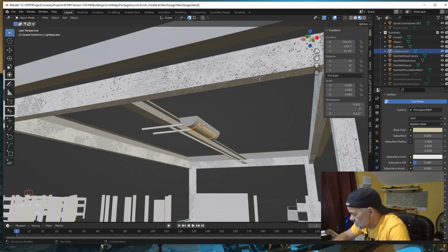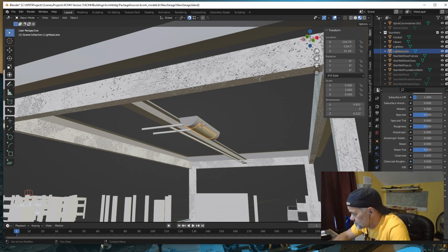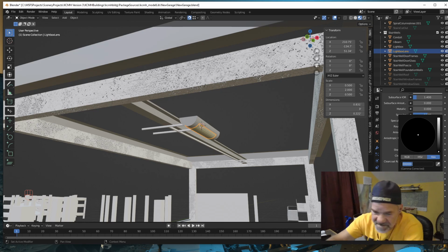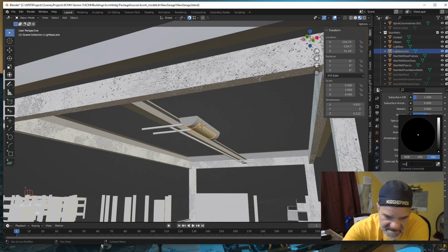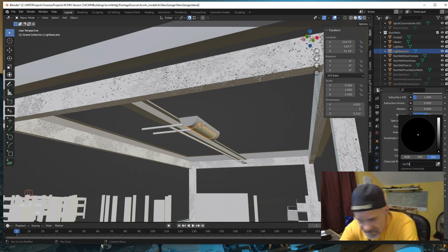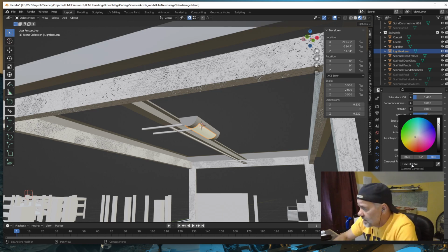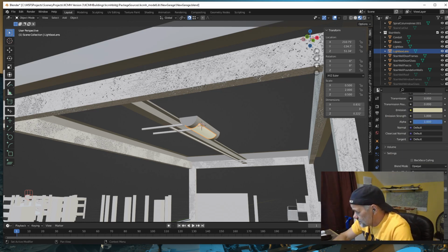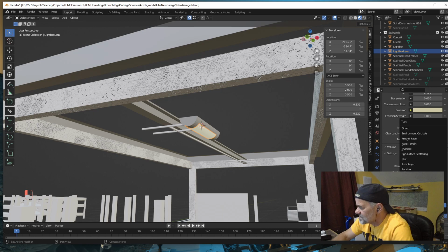All right, now that I know that, let's come down to emission and select emission, go to hex, and type in CCC7 alpha 3. Hit enter. So now, oh, I did that wrong. I didn't do it wrong, I just should have done it a different way. Sorry, that's what you get for watching this live, right? It's not live, but you know what I mean. Let's go down to MSFS material parameters and change that to standard.